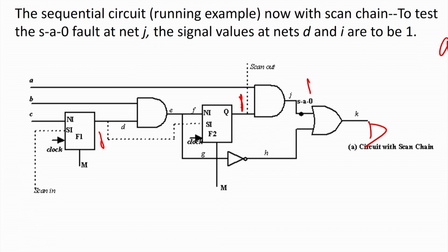So now what is the one way? If we are using a propagation, I am not going to discuss the old story, in which case without using any scan chain business, if you want to make both the flops 1, you can do it, but you will require 2 or more patterns for that. Because to make the first flip flop 1, you have to apply C equal to 1 and apply a clock pulse. The first flip flop output will be directly equal to 1. But then at the second step, you have to make B equal to 1.